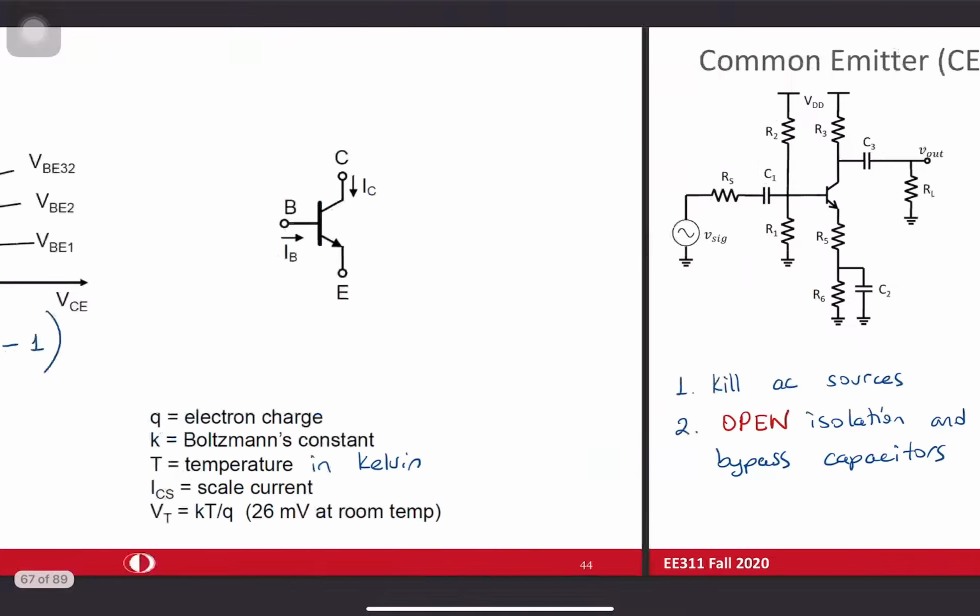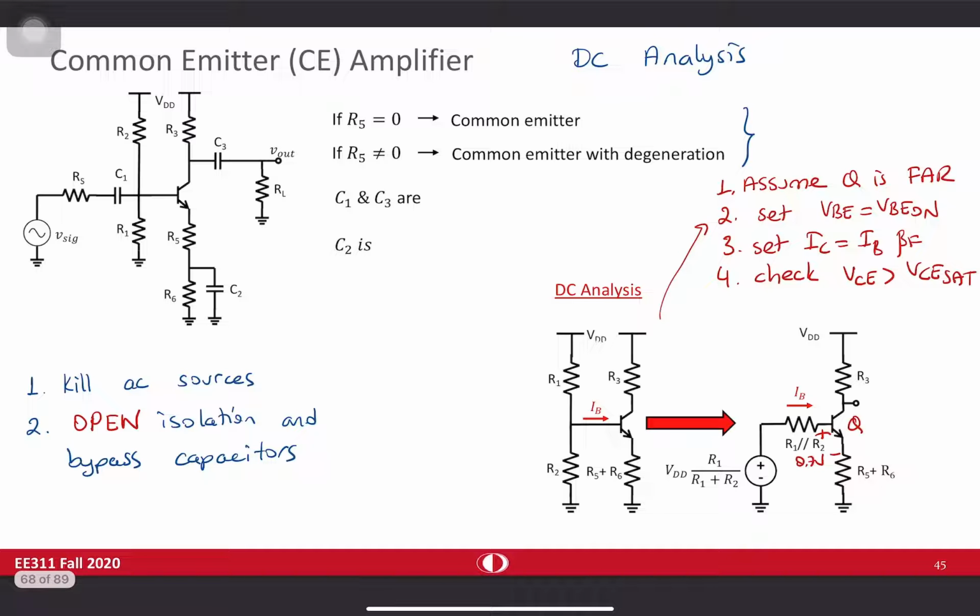In the DC schematic, these two resistances, R1 and R2, cannot be selected as very high. Why? Because they are appearing in the Thevenin equivalent circuit. As you increase R1 and R2 value, the potential drop across this resistor will be more, and you can transfer only some part of VDD voltage to bias the transistor. So it's a big trouble. You cannot choose giga-ohm resistances. You have to choose lower resistances at the input.